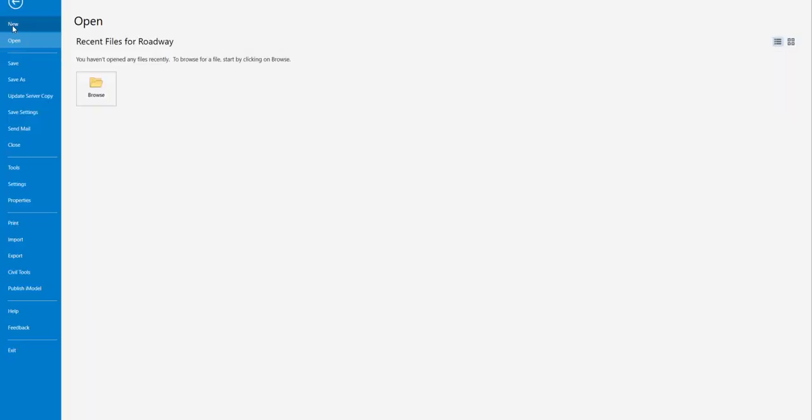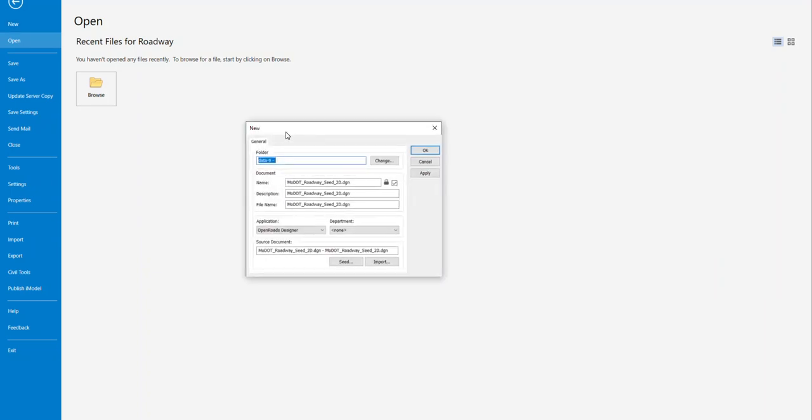Do a file, new. And then make sure you're in Data 9. And we are using a 2D file again. So we'll go ahead and paste in that file name and do a backspace to get rid of that space. So the name of this file is going to be named underscore boundary underscore plan dash profile underscore route dash 54 underscore J5P3181.dgn. So if you've got it like I have it, you can hit the OK button. And we'll create that brand new blank file.